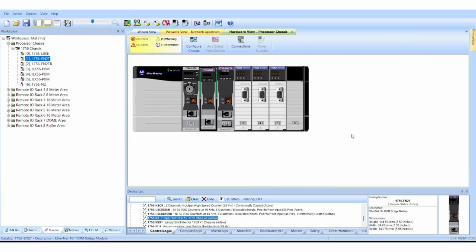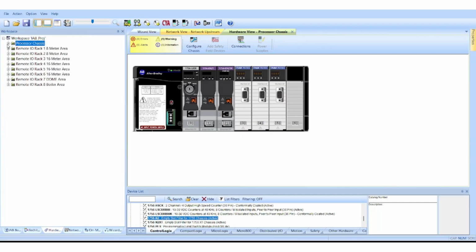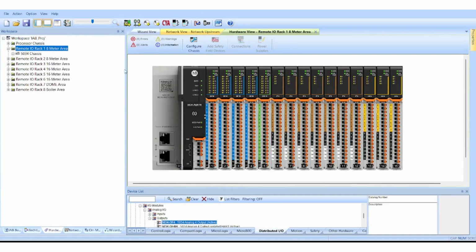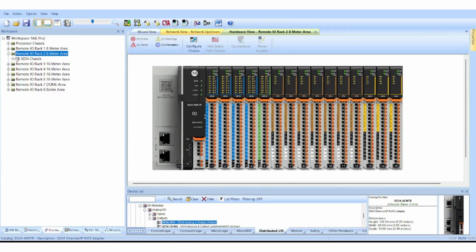These MCCs contain a large number of motor control devices, including DOL starters, soft starters, and variable frequency drives, so their communication and integration must also be considered as part of the complete automation architecture. Again, the important point is that we are not designing the PLC, I/O, MCC communication, and network as separate systems. They are all parts of one integrated automation solution.